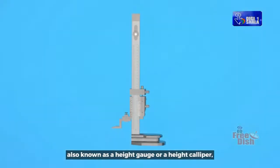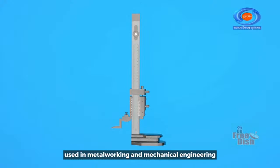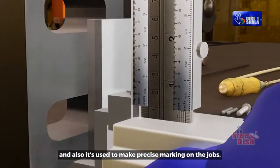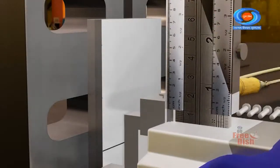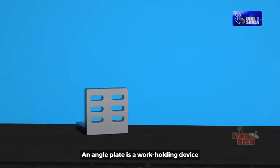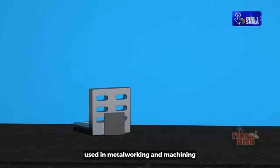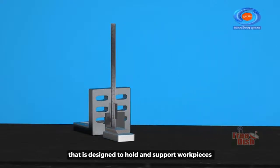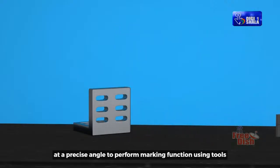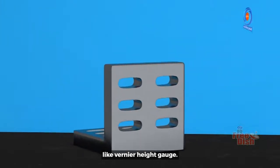Vernier height gauge. A vernier height gauge, also known as a height gauge or a height caliper, is a precision measuring instrument used in metalworking and mechanical engineering to measure the height of objects, and it is also used to make precise markings on the jobs. Angle plate. An angle plate is a work-holding device used in metalworking and machining that is designed to hold and support workpieces at a precise angle to perform marking functions using tools like the vernier height gauge.